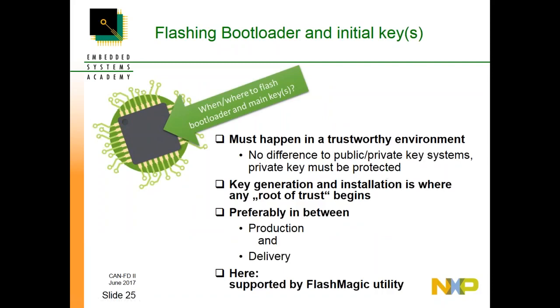Now with all keys, one of the biggest questions is, when and where are they installed originally? At some point they need to get into the system. Well, this must happen in a trustworthy environment. And this is really not too different from public-private key systems. In a public-private key system, yes, you can throw the public key around openly. However, the private key, you also have to be very careful where you use it and where you keep it, and it needs to be very protected and only installed in a trustworthy environment. And so really that's where a root of trust begins.